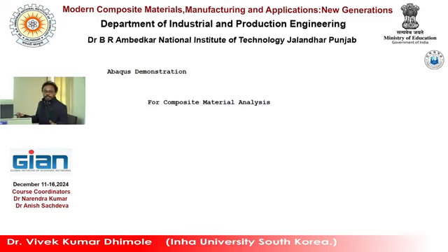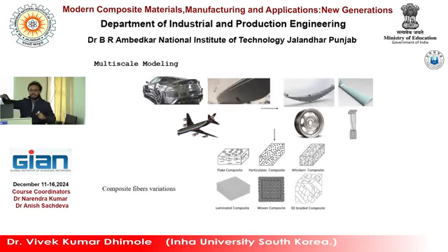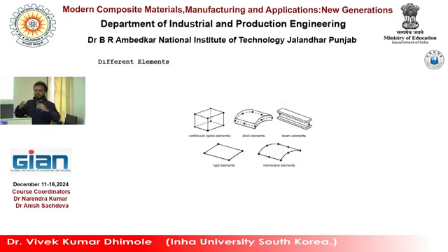That is for the supporting one, either something like that, right? So different kinds of elements we have. The membrane element is for the curvature one. When we have large curvatures and a long thin film, then we use the membrane element, right? You can say plane strain kind of things, okay? So these are different elements. We have the plane stress element, many elements, you can understand those things. And I just show a few elements, right? Now I will show you the Abaqus demonstration.